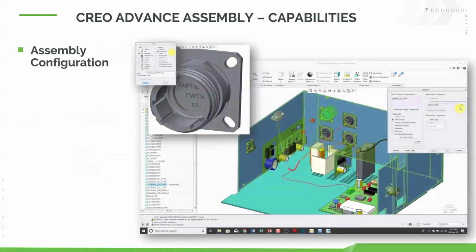We also have the idea of assembly configuration. We have tools such as interchange groups for things like fastener attachments, where they're always going to go on the same way. You shouldn't have to spend a lot of time setting that individually. So maybe if it's something like a custom electronic fitting where we're just trying to make it mount, all we have to do is pick a face where it's going to go, give it a location, and it's going to be able to be changed up depending on what your order might be or what type of configuration that you're working with here.